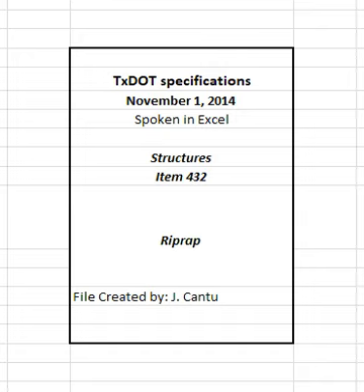3.2.3 Common. Construct riprap as shown in Figure 4 on the stone riprap standard. Place stones on a bed excavated for the base course. Bed the base course of stone well into the ground with the edges in contact. Bed and place each succeeding course in even contact with the preceding course. Use spalls and small stones to fill any open joints and voids in the riprap. Ensure the finished surface presents an even, tight surface, true to the line and grades of the typical sections.